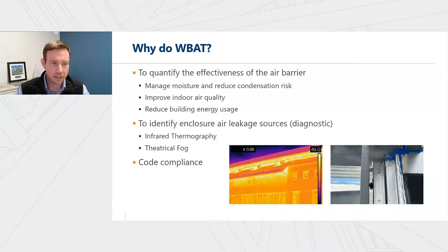The second main reason is to identify enclosure air leakage sources and sites through diagnostic testing. Diagnostic testing helps highlight the areas of air leakage so they can be remediated before they become covered up with cladding and potentially become a problem in the future.